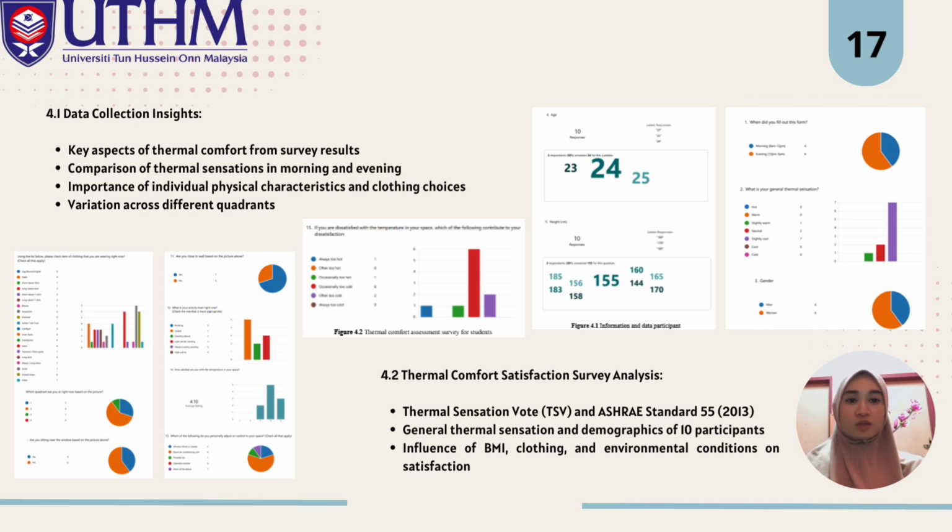Next, for our thermal comfort certification survey analysis, we analyzed the thermal comfort survey. We used the thermal sensation vote, TSV, in line with ASHRAE Standard 55 from the year 2013. This helps us understand the general thermal sensation and demography of participants. Factors like BMI, clothing, and environmental conditions play a crucial role in determining comfort level.